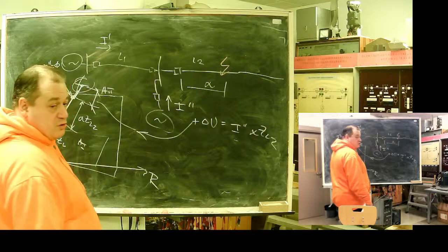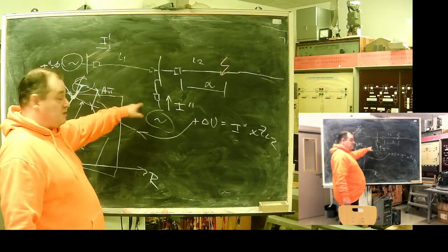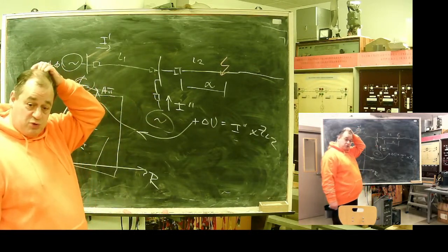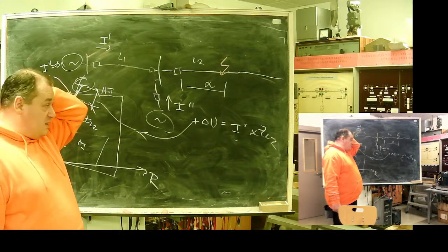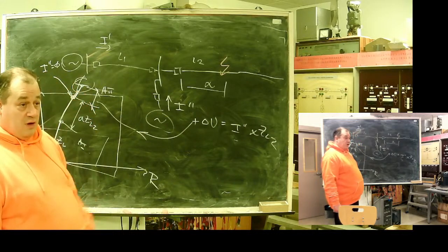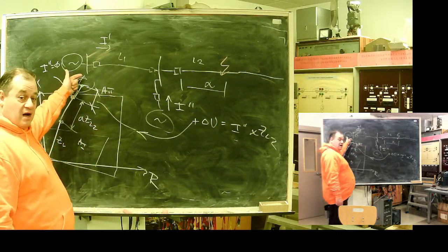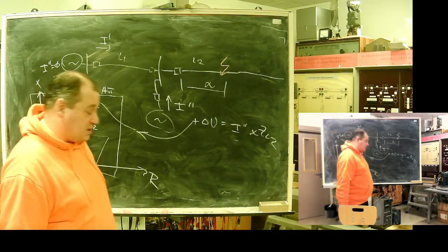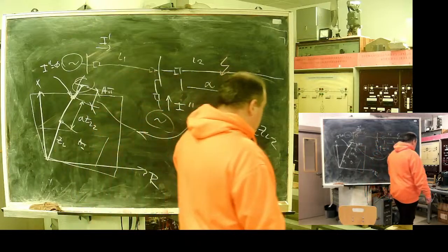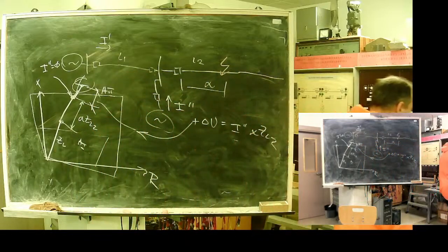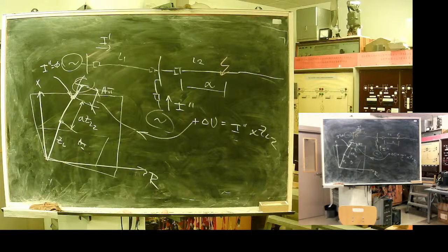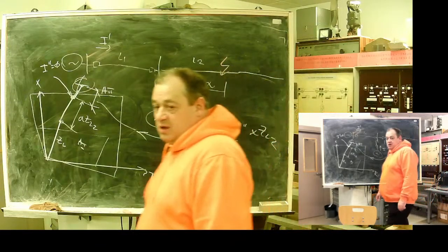The parameter used to characterize this is called the current distribution factor. It's a ratio between the fault current and the current observed by our protective relay. In case the relay observes the full current, it will be 1. In case, for example, the currents are equal, it will be 1/2.